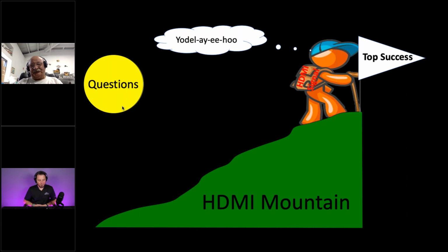So, next question. I regularly read EDIDs from TVs that I test and review. Before the readout, I always set the HDMI parameters to enhanced, which makes sense, especially with the newer TVs. I usually get 1190 megahertz as a maximum pixel clock. Can you confirm or deny that this is the maximum pixel clock stipulated by HDMI 2.1? Unfortunately, some TVs show the maximum pixel clock of only 600, even when they're in an HDMI 2.1 mode. Does that mean that the 2.1 ports are somewhat compromised? Catch all that? What was the first number?